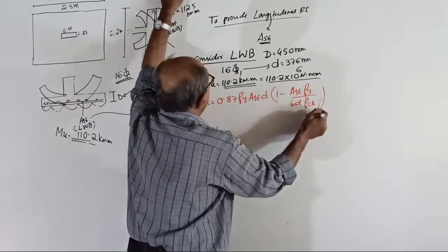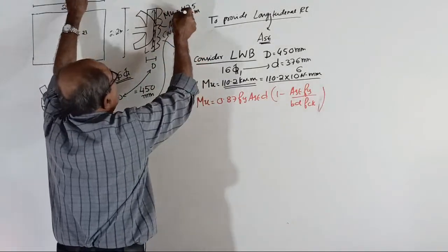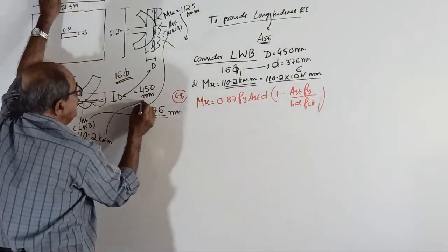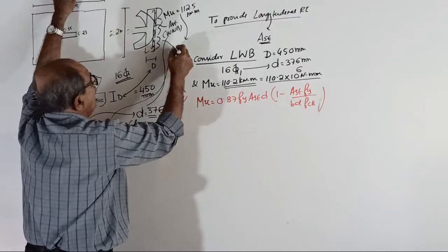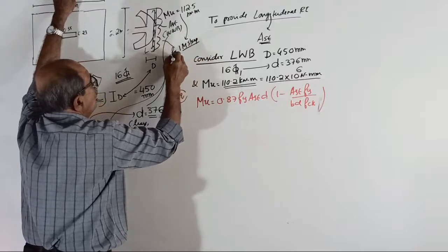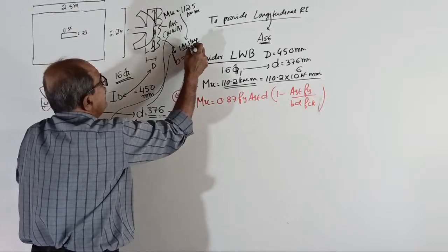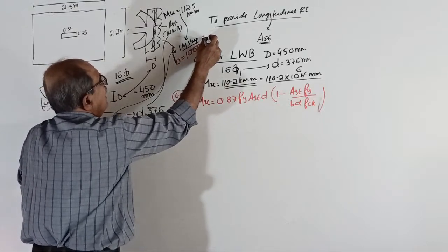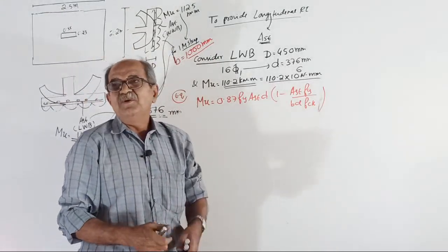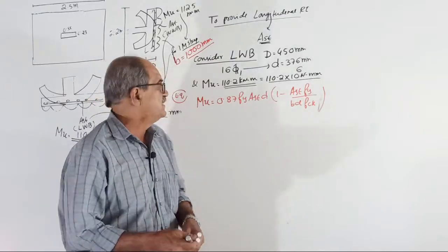One important thing: you should write both these bending moments, Mu equal to 112.5 and the other Mu equal to 110 point something, are for a 1 meter strip. I told you, therefore wherever your b comes, b is 1000 millimeter. I am only wasting time telling this. When you take a 1 meter strip, your b equals 1 meter. Okay, start.